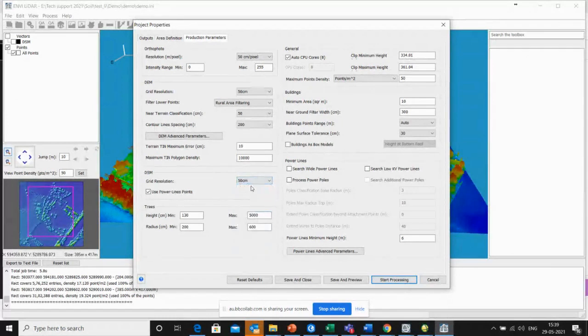So now go to the 50 centimeter setting, and you can see the building level. Building level is 10 centimeter if you require; you can go for the 10. Here this is a point cloud, a point cloud per meter square. This is 50, and we have 32, so we can go for 30 also. Accordingly, you can give the minimum point density you require for the particular objects which you are going to create.